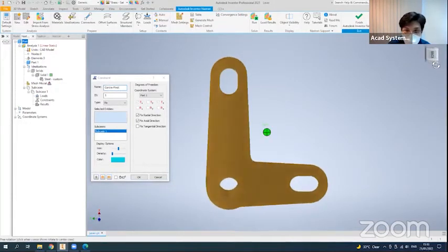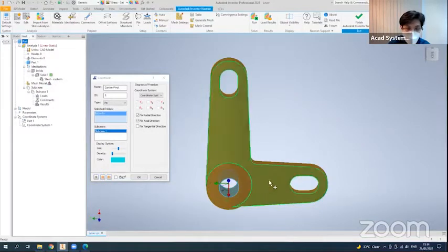Let me now select the face. Select entity stands for selecting the face that you want to apply the constraint to. I'll be selecting this inner face. Make sure you select the right face, the face highlighted in blue. Then you click on preview. Preview, or this spectacle right here, allows you to look at the constraint forcing that is applied to your structure. So for the center pivot, click on this preview.